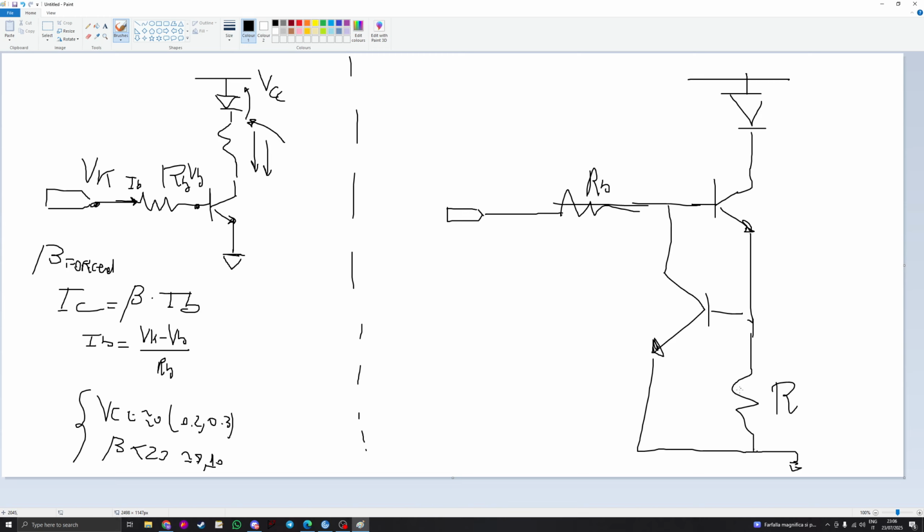Basically, you make this resistor active, so you design the drop voltage of this resistor so that the collector of the transistor Q2 drains a little bit of the base current, and it will keep this current constant.